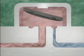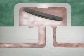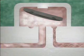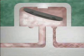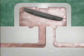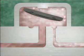During normal operation, hot condensate entering the trap experiences an increase in velocity and a reduction in pressure. As a result, some of the liquid condensate changes state, flashing to steam. Because steam has a greater volume than an equivalent weight of condensate, the velocity of the flow through the trap greatly increases after the flash steam has been generated. This further increase in velocity reduces pressure on the underside of the disc. At the same time, flashing condensate flows out and causes a pressure buildup in the area above the disc.